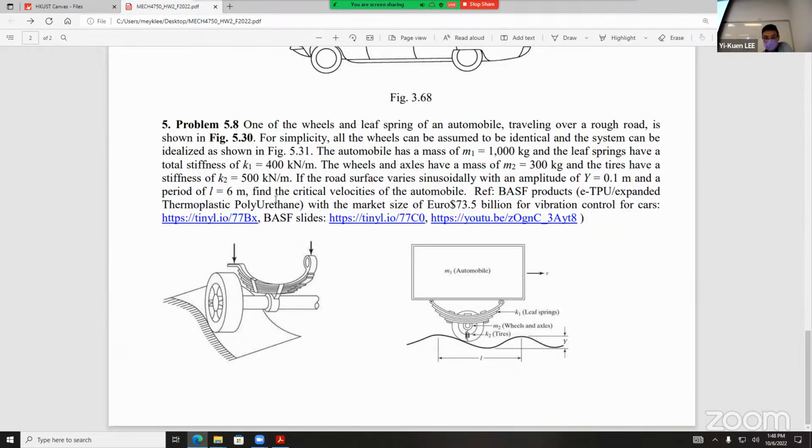So what we care about is why this is important. Because this is polymer, right? Remember, polymer with higher damping. Remember we talked about it in our lecture notes. In many cars we may use metal to make our structure, and the damping of metal is so small. That's why in this case we may need to introduce some viscoelastic material to control the vibration amplitude, so that the people inside the car will feel comfortable. If you use 100% metal for your car, people inside will feel very bad.